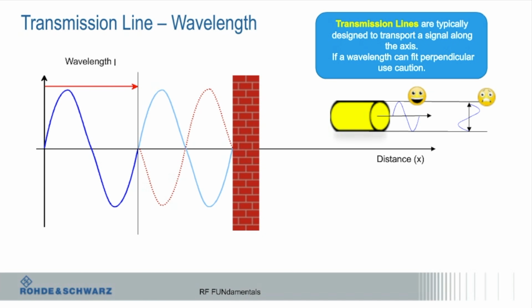They're typically designed to transport a signal along an axis. One thing, just a cautionary note, often you need to turn when you're using a cable or a transmission line. Avoid right angles. I've seen stuff where they actually measured current density on some instruments, and you'd be amazed how much things change when you take a sharp turn. It really degrades the performance a lot, so try to avoid that. Just think of it like flowing like a pipe, really.